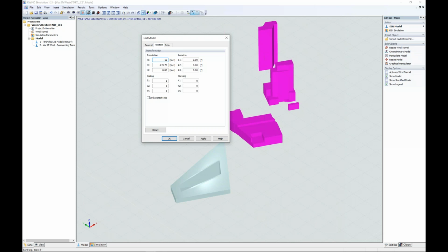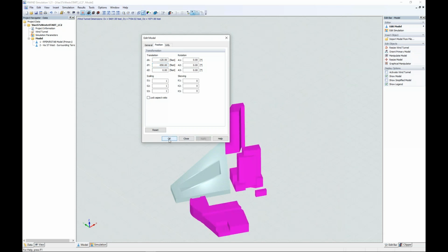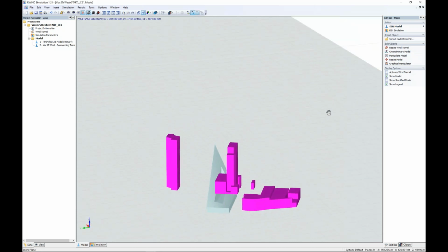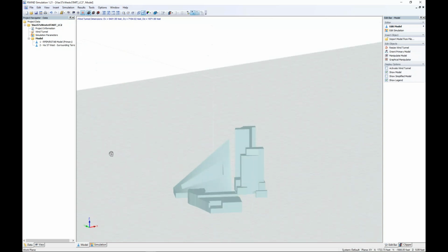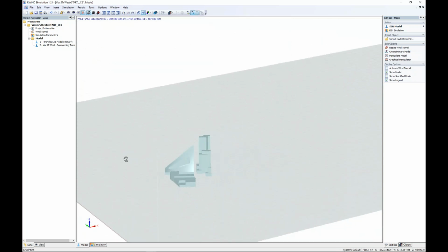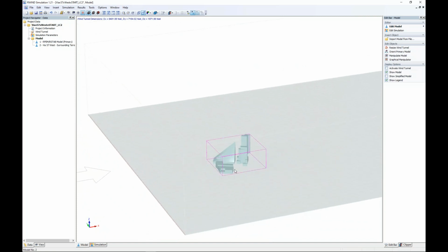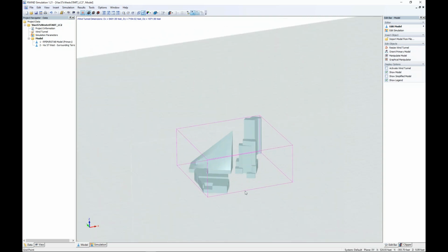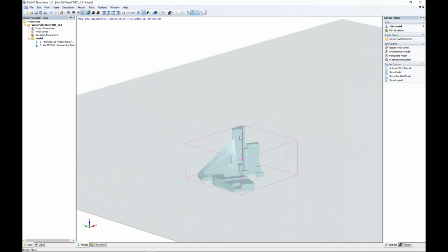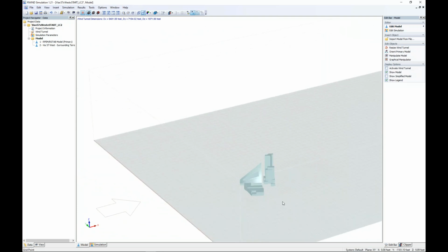And for today, I want to modify to a negative 120 feet in the X and negative 950 feet in the Y. I click apply, I can hit OK, and now we can see how these adjacent structures sit right next to the building in question. So inevitably, this is why I want to account for these adjacent structures, because I know that the wind loading is going to be affected based on where these are located. And you can imagine that when we start to consider wind loads, especially in the 180-degree direction, it's going to be significantly impacted by these rear structures.